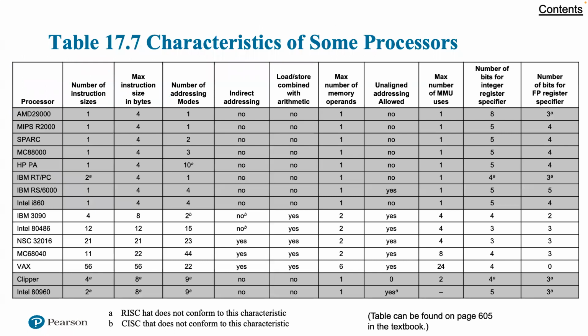After the initial enthusiasm for RISC machines, there has been a growing realization that one, RISC designs may benefit from the inclusion of some CISC features, and two, CISC designs may benefit from the inclusion of some RISC features. So it's hard to find the best of both worlds, in other words. The result is that the more recent RISC designs, notably the PowerPC, which is a little bit older now but still an example of a RISC processor, are no longer, quote, pure RISC, and that the more recent CISC designs, and so we can be thinking about the Pentium 2 and later Pentium models, do incorporate some RISC characteristics.